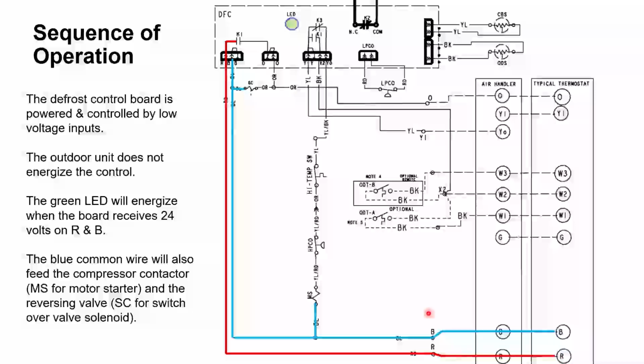And it can be really difficult when one of the FSRs comes out to the job because you've changed the defrost control board 3 times, and we show up and this LED on the board is not lit, and we say, hey, check 24 volts, and we don't have 24 volts on that board. And we say, well, you've got to get 24 volts to the board, otherwise it'll never go into defrost. And people say, well, but the unit ran just fine, except it won't defrost. Yep, that's correct. Without 24 volts, it will not defrost, but it will run in heating and cooling.